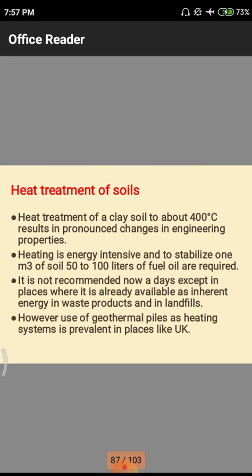That means temperature is used, so to create an artificial temperature in the soil, automatically we require some fuel, like crude oil or other natural oils, which will be used as a fuel. Simply for every meter cube of soil, we need to raise the temperature. Automatically those will consume 50 to 100 liters of fuel, so it is a very costly process.